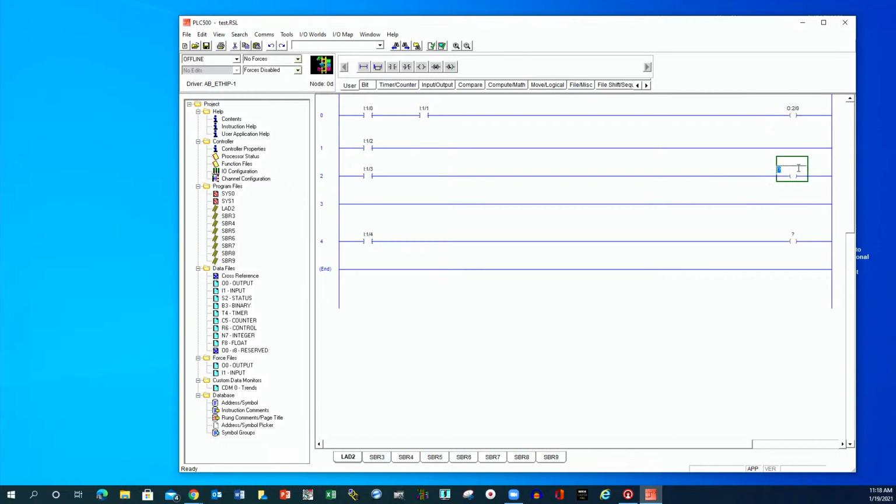This thing will let you put a 0 instead of an O and a 1 instead of an I, but it will not run it. When you go to run it, it's not going to throw an error like a normal PLC would, because normally it would say, nope, this isn't a valid word. If I was to put a 0 here instead of an O, it would accept it, but it would not run it in the simulator. It just wouldn't turn on. It wouldn't know who to talk to. So at least that part works nicely.